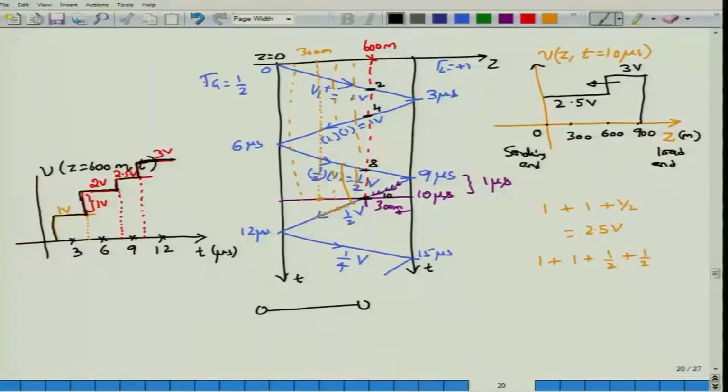Well, remember, this is an open circuit, right, and an open circuit would have a full voltage across it, and the line is lossless. So, no matter what line we have connected, as long as it is lossless, the voltage that you would see on an open circuited end of the transmission line will be the full value of Vg. So, here you had some Rg, and after the time where the transients have settled down and you have reached the steady state, you should see a full voltage of Vg, and that would be the voltage distribution along the entire length. What would be the current distribution?